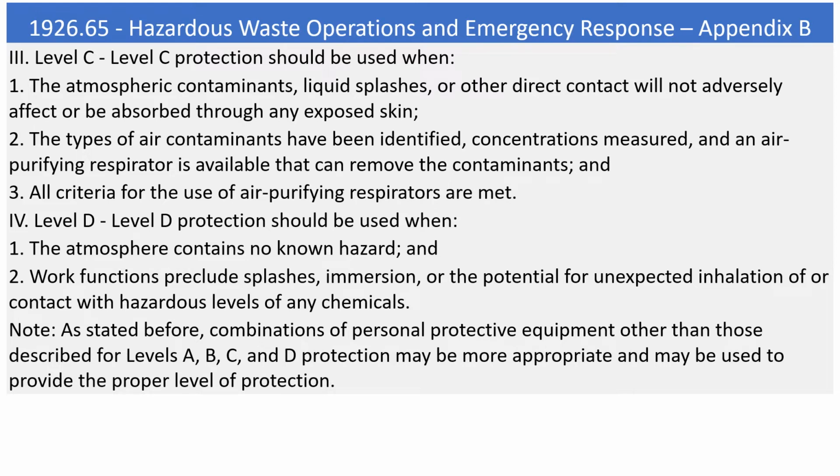4. Level D. Level D protection should be used when 1. The atmosphere contains no known hazard, and 2. Work functions preclude splashes, immersion, or the potential for unexpected inhalation of or contact with hazardous levels of any chemicals. Note: as stated before, combinations of personal protective equipment other than those described for levels A, B, C, and D protection may be more appropriate and may be used to provide the proper level of protection.